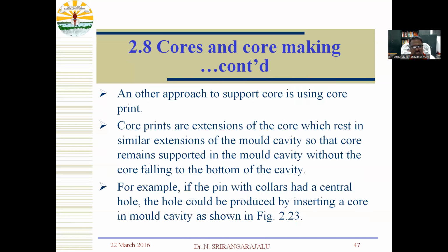So cores and core making: another approach to support the core is using core prints. Core prints are extensions of the core which rest in a similar extension of the mold cavity, so that the core remains supported in the mold cavity without falling to the bottom of the cavity.